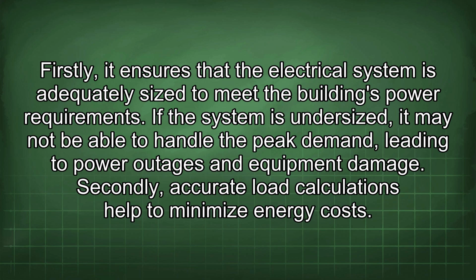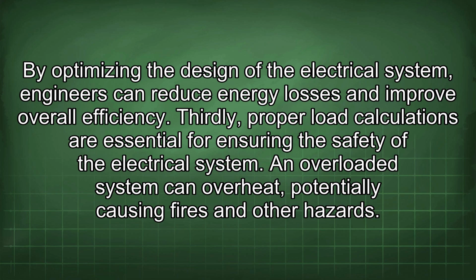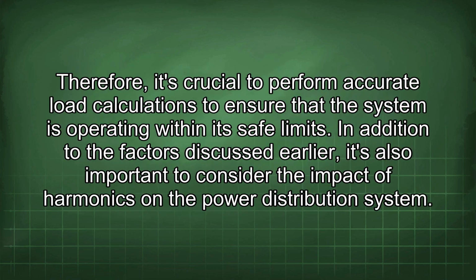Secondly, accurate load calculations help to minimize energy costs. By optimizing the design of the electrical system, engineers can reduce energy losses and improve overall efficiency. Thirdly, proper load calculations are essential for ensuring the safety of the electrical system. An overloaded system can overheat, potentially causing fires and other hazards. Therefore, it's crucial to perform accurate load calculations to ensure that the system is operating within its safe limits.